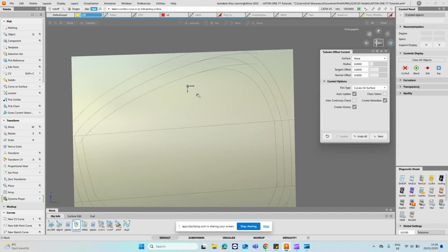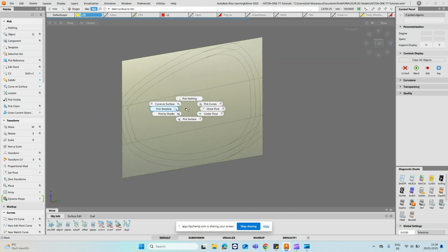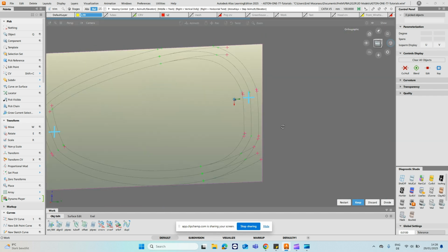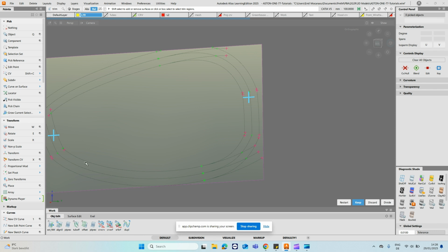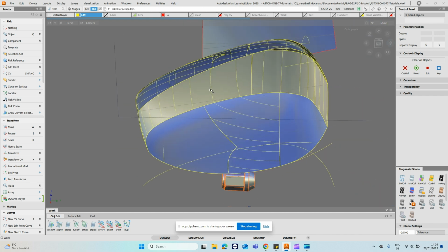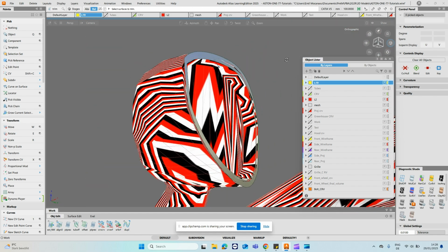That's it. And now I just trim everything over the excess away, and for that I'll take these two curves and surface, hide them, and I want to keep this inner bit here. So set your crosses where they need to sit, and I've identified that half of a loop and then that bit there. That does it. Now let's bring back the mesh and check it out.